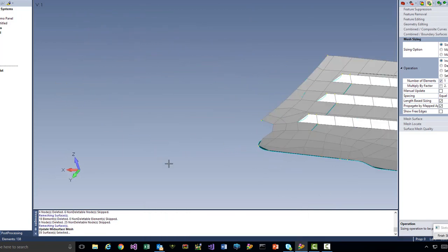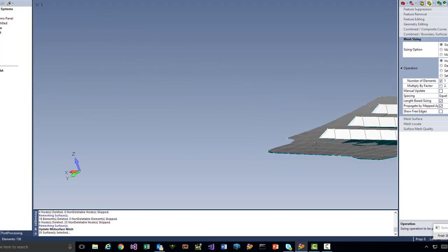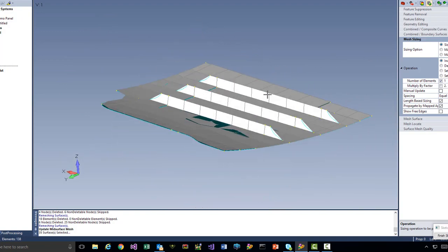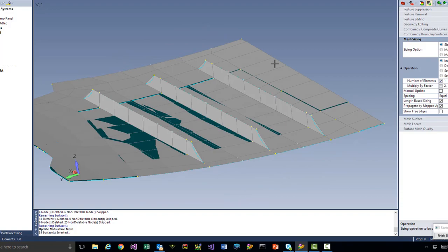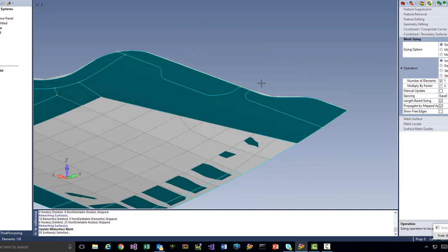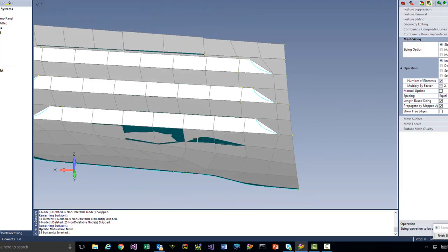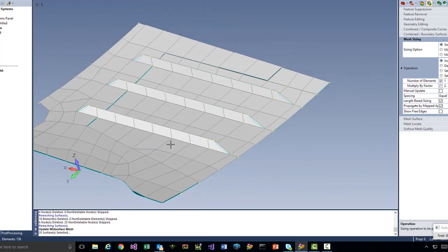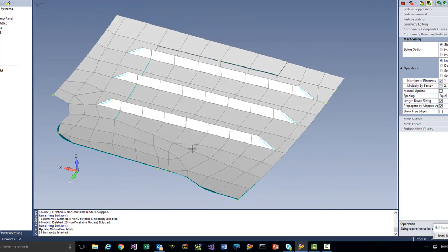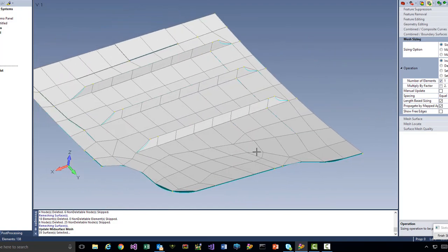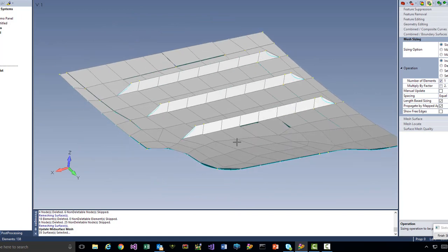It sets up the thickness and offset to match the original solids. You kind of get those padded up and down regions on your part. So the thicknesses more or less match the original solid. So for a coarse mesh, it's about as good as you're going to get. Now let's do that beam thing.